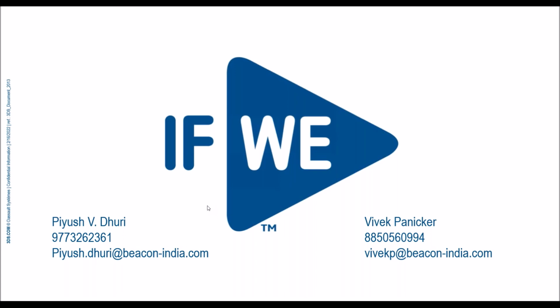Is fatigue, modal and harmonic analysis supported? Yes, we have support for fatigue analysis inside the same window. We have a role called durability engineer. Modal and harmonic are supported in the same environment that we have showcased. Is nonlinear contact analysis without node bonding possible? Of course, sir. In what we have showcased, in some of the nonlinear analyses we did not make any compatible mesh, and the node-to-node connectivity can be totally controlled by the contact we have defined.